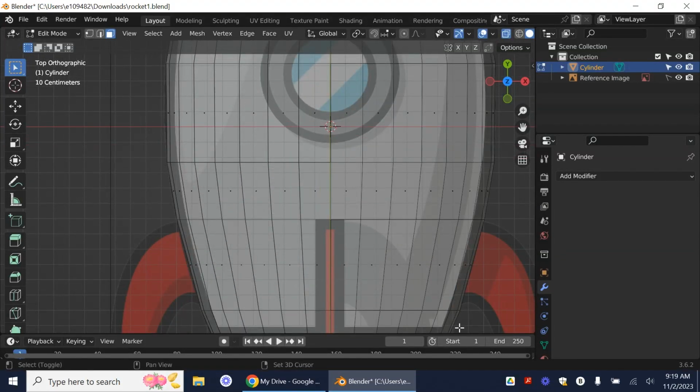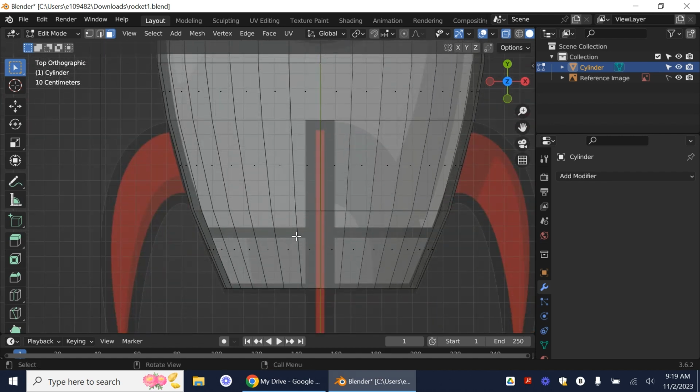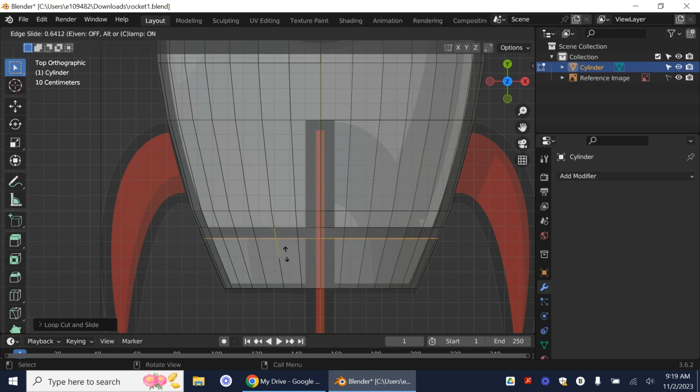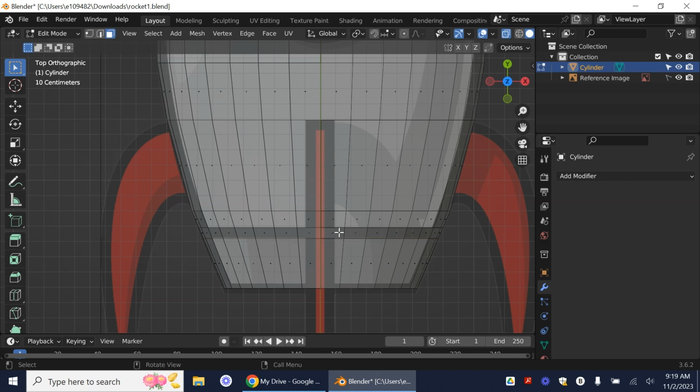So I'm going to need to create 2 loop cuts here. So I'm going to push Control R, and put one here, and then Control R, and put one here. Okay, again, I don't know how I got in a different mode, but face select, hold down the Alt key. I need to probably check that one if I was in the right mode.